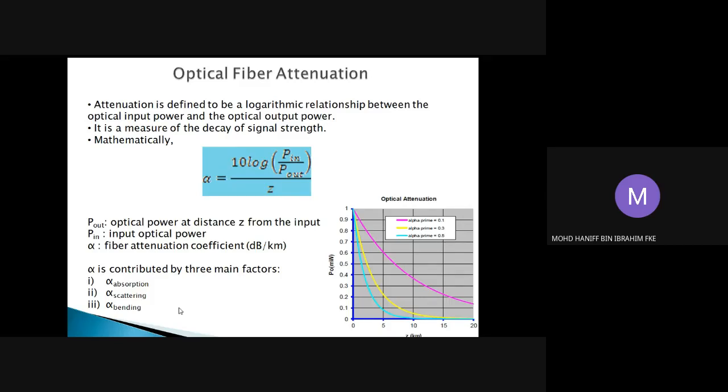the polymer based fiber, the black colored fiber, which has a very high loss as compared to commercially used fiber optics for communication, which is silica base. Silica base has a very small value, about 0.1 or 0.2 dB per kilometer, as compared to polymer base, which is higher. But I believe that should be some sort of exposure to the students on fiber optics communication. It's actually good.